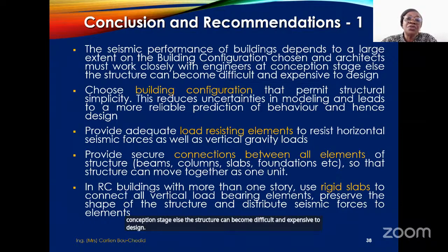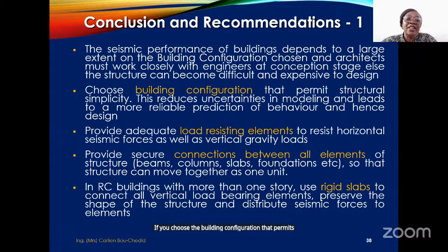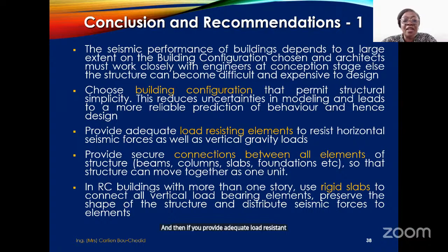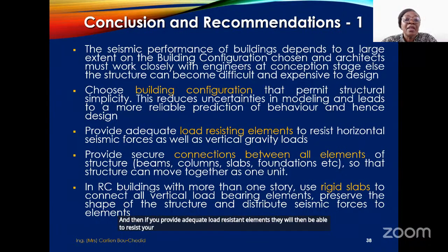If you choose the building configuration that permits structural simplicity, you reduce the uncertainties in the modeling, and you can have a more reliable prediction of behavior and hence design. And then if you provide adequate load resisting elements, they will then be able to resist your horizontal loads as well as your vertical loads.